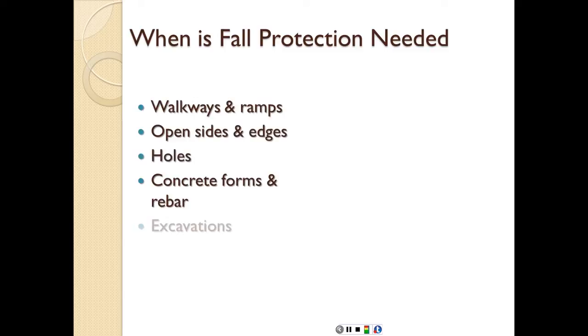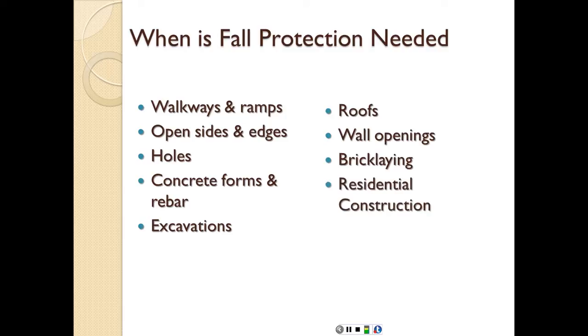So when is fall protection needed? It's needed on all of these: walkways and ramps, open sides and edges, holes, concrete forms and rebar, excavations, roofs, whether they're low slope or high slope, wall openings, bricklaying, and residential construction.